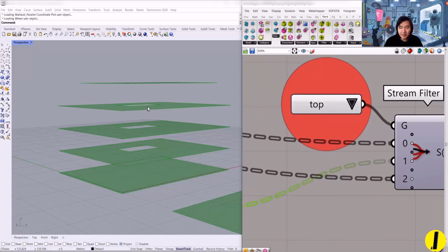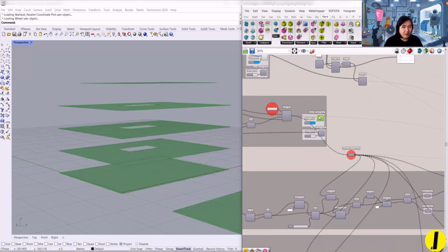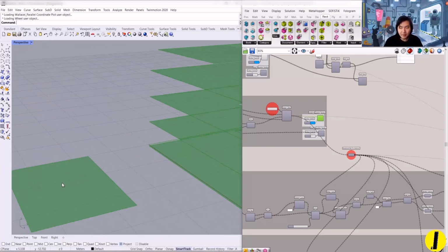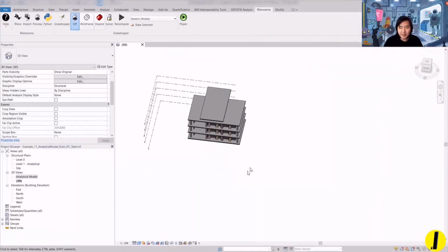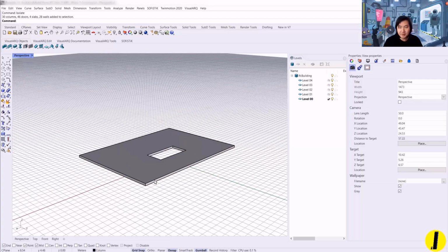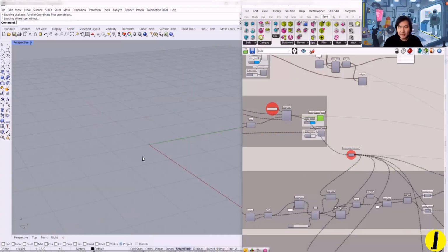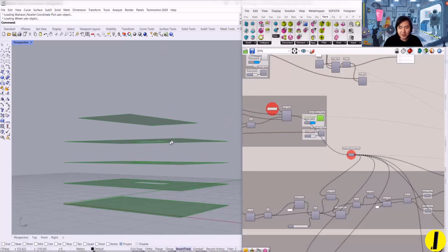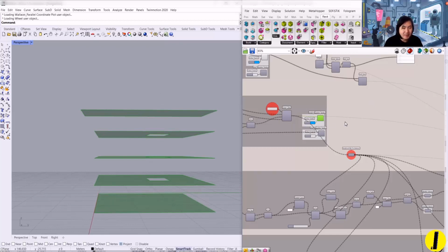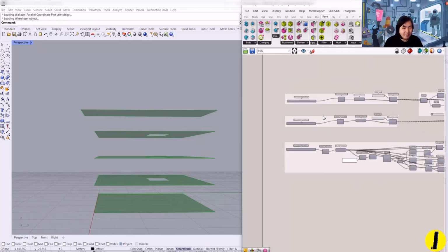Of course, you can define later if it's top or center, but we'll skip that. You have the slab here, and it shows the slab just because I drew the Revit slab. Somehow it isn't. Let me recompute. Recompute refreshes your script with RhinoInside. So now if you look, it brings only the slab we have from the IFC model instead of Revit elements. Alright, so the slab is done.